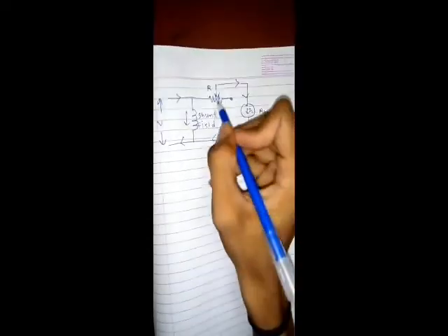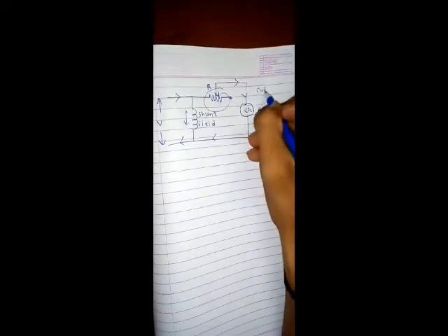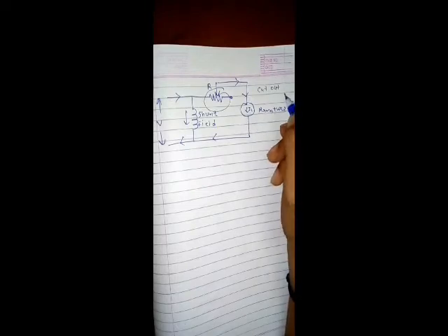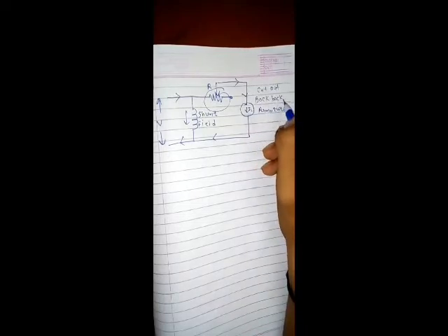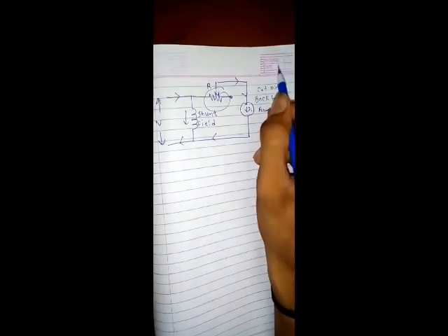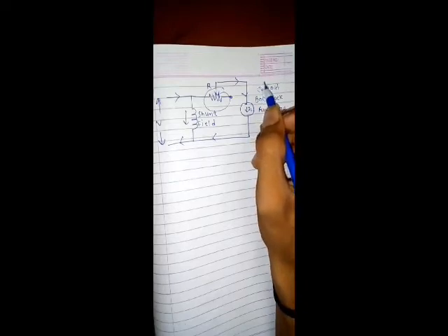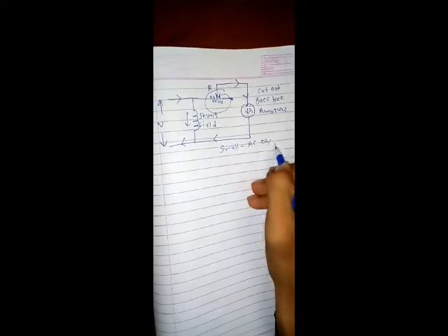The starting resistance is gradually cut out as the motor gains speed and develops the back EMF, which regulates its speed. Very small motors, like small AC motors and small DC motors, may however be started from rest by connecting them directly to the supply line.